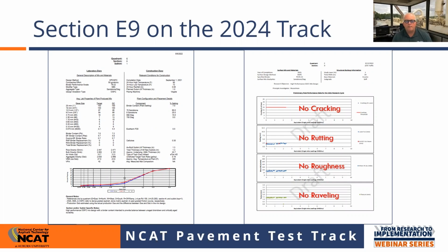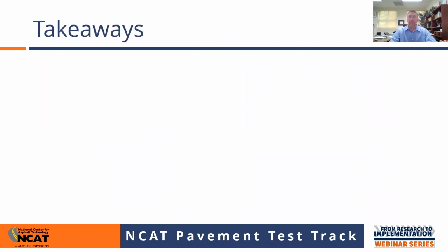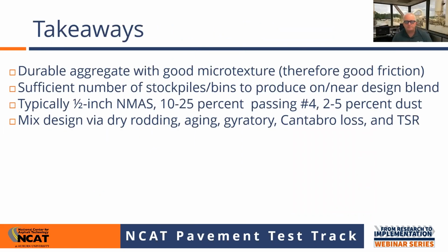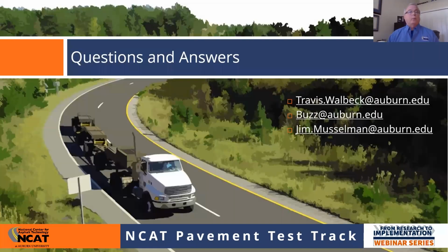Okay, great. If we're going to use a ground tire rubber type of binder, would you put an extra gap in an OGFC, or would you design it any differently? Jim, you want to take that? Yeah, my 2 cents would be no. I think you've got enough openness in that gradation that you wouldn't need it.